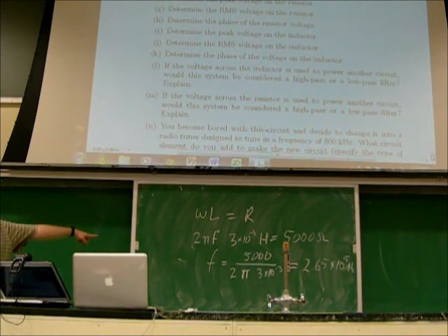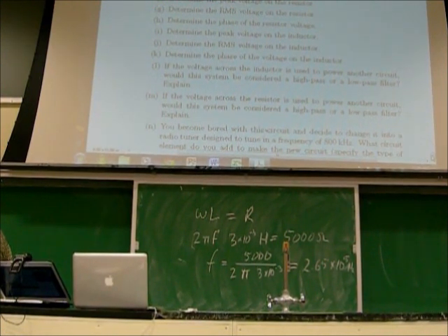In our case, what did we send in with 5 kilohertz? Higher than this or lower than this? Lower. So, the resistor got it all. So if you were a circuit in parallel with the resistor, you got all of it, because you were on one side of a low pass. If, on the other hand, you were a circuit in parallel with the inductor, you got less than a couple tenths of a volt.